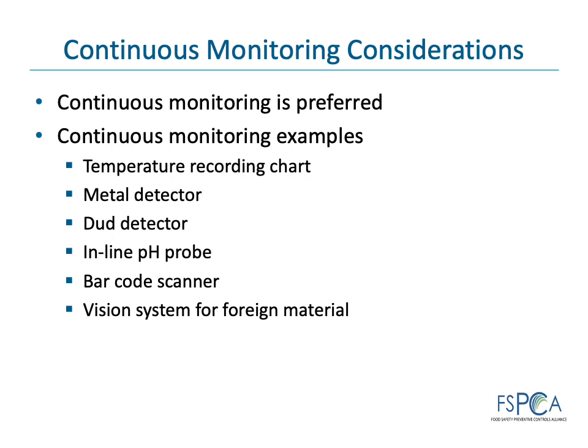The proper functioning and automated records generated, if any, for each of these types of systems must be monitored or verified, as appropriate, see below on exception records, by an individual on a periodic basis to document that the system is performing as specified in the food safety plan. For example, the ORP readings may be read twice a shift by a line operator in addition to the continuous record. The term continuous monitoring may be interpreted differently by some.